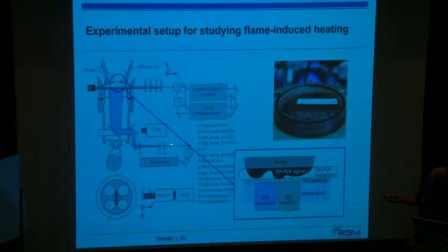And simultaneously in the same cycles another laser was used. This was a high repetition rate UV laser where we were exciting the phosphorescence from below. It was a very thin coating. We controlled that. When we produced it, it was in the order of 10 microns and very reproducibly coated. And then the phosphorescence as well was imaged in the same direction, because there was no space left really to look from the top on this coating. It was then traced back to this other high-speed camera.